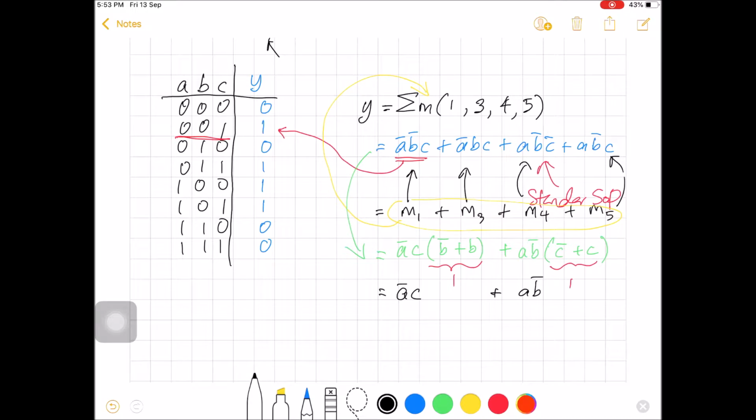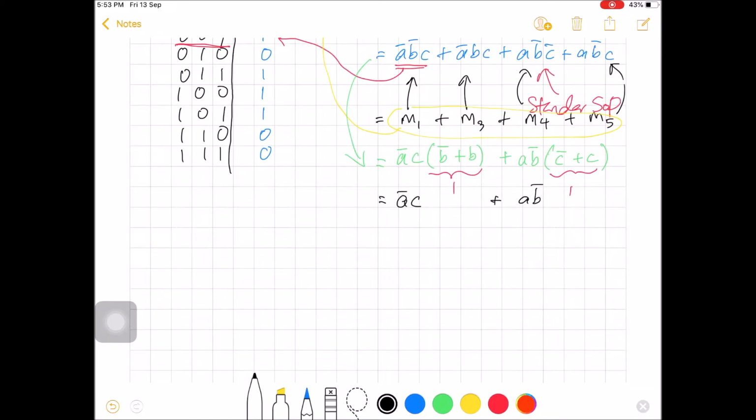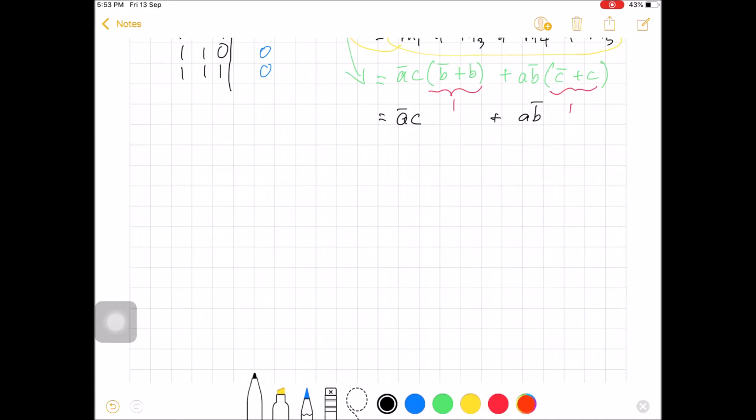Alright, we can also derive the Boolean logic expression using the famous Karnaugh map, or we often call it K-map. Here we can simply build an 8 cells K-map that corresponds to the 3 input variables A, B, C, like this.